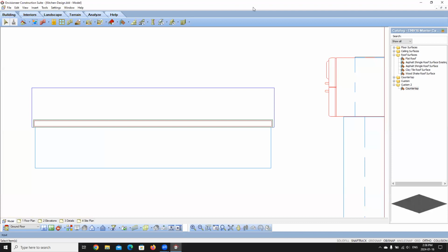So Envisioneer provides a number of building and editing tools to help you create virtually any kitchen design. The Kitchen Builder Wizard builds a complete kitchen for you automatically based on settings that you define. You can edit the individual components to suit your design needs. You can use the cabinet tool to insert individual cabinets wherever needed, and you can also simply select the cabinet that's been inserted and replace it with any other cabinet that you need. Each individual cabinet can be customized, moved, or deleted.